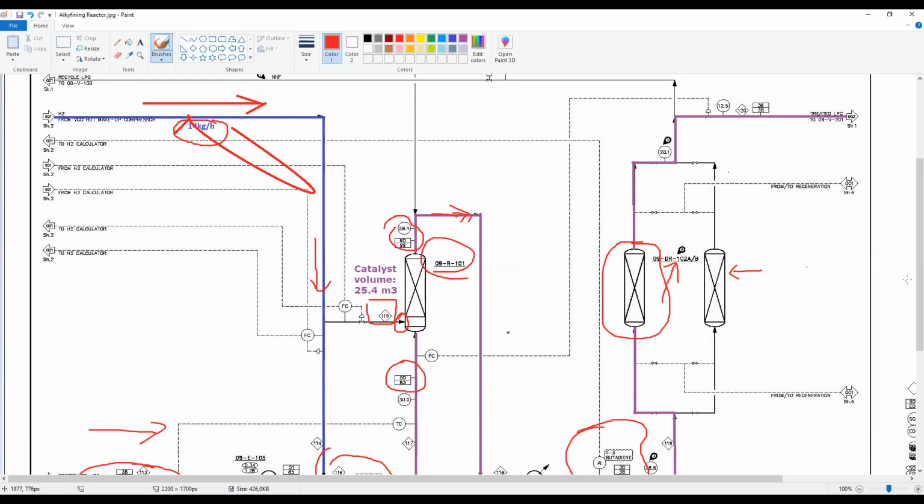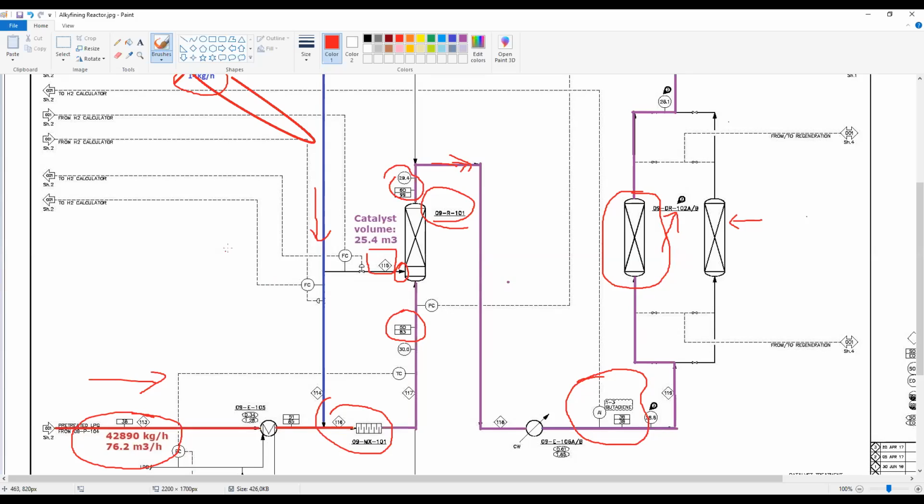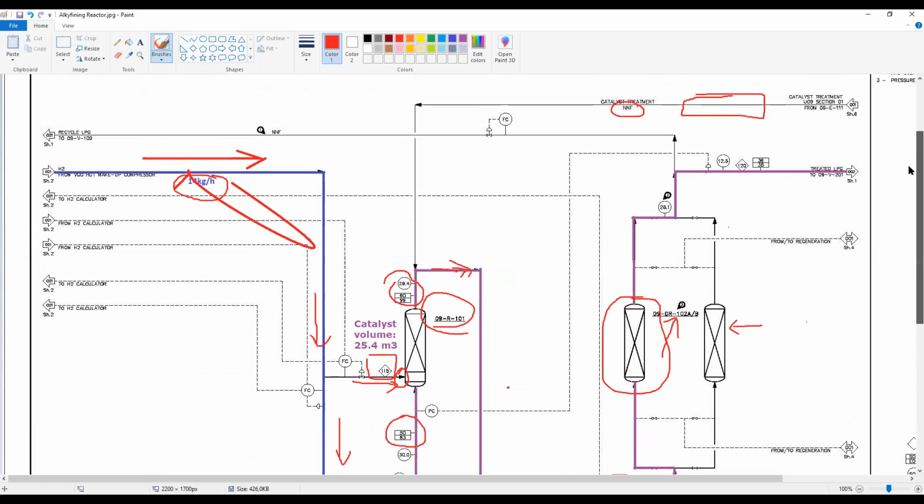They have put this other way to add hydrogen because this quantity of 14 kilograms per hour is more related to the solubility of the hydrogen in the feedstock. So, a quantity of hydrogen will go to the mixer and the rest of the hydrogen will go directly to special distributors in the reactor. Well, this is more or less the reaction section of this first section of the polynaphtha unit. Then we will continue with the presentation.